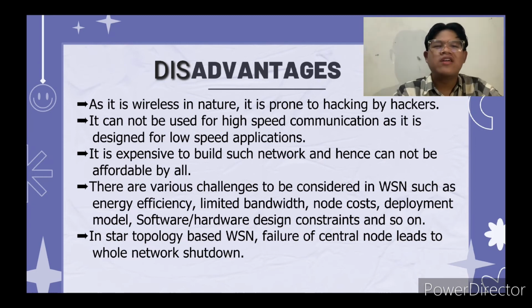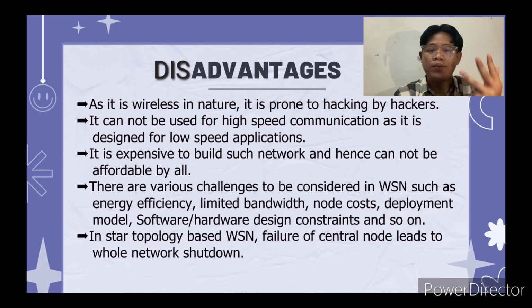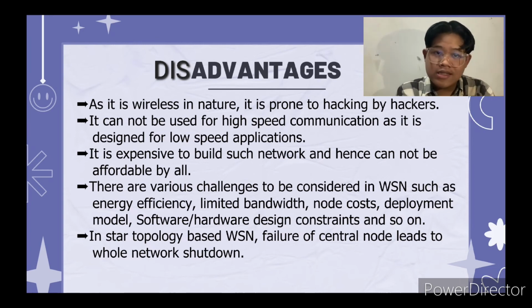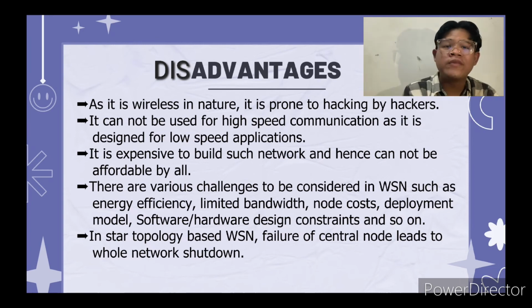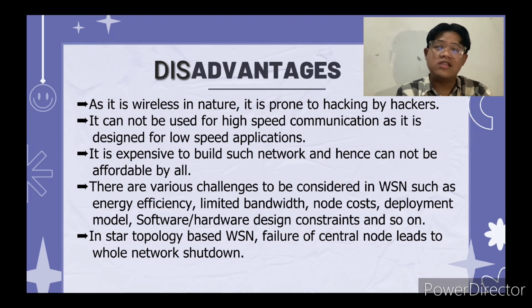Fourth, there are various challenges to be considered in USN, such as energy efficiency, limited bandwidth, node cost, deployment model, software or hardware design constraints, and so on. Lastly, the disadvantage is the star topology based USN. Failure of the central node leads to whole network shutdown, meaning that if the central node fails, the whole network in one place shuts down.